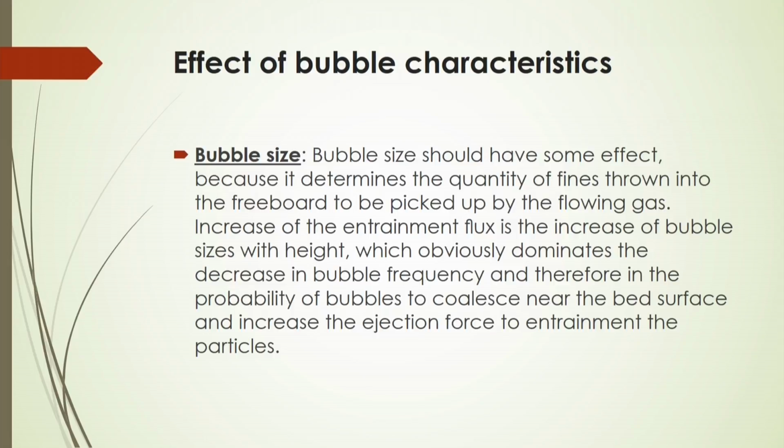Of course, you will see you will get fewer bubbles there, and therefore a higher probability of bubbles coalescing near the bed surface, which increases the ejection force there to entrain the solid particles. So, in this way the bubble size will affect the entrainment rate.